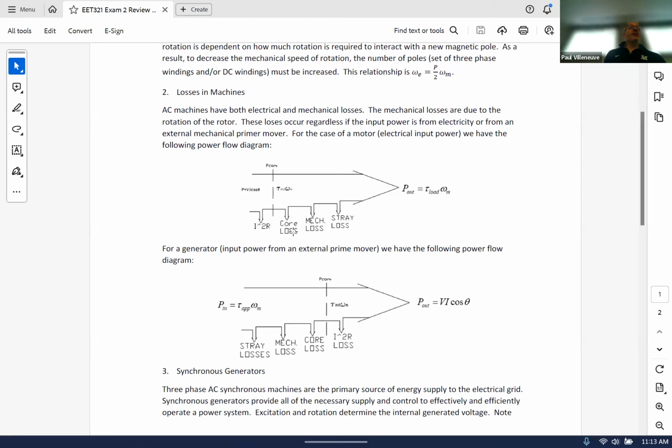Over here, we are still in the electrical world. We're losing power in the magnetic core. So we haven't converted anything to a torque yet. We're getting close. So this power over here converts from the stator to the rotor. Over here, this would almost be like a developed power, which is the torque that we have. That's developed torque. Once we get beyond this point, all the losses we would consider are some sort of mechanical loss. And then what we end up with is our output torque.